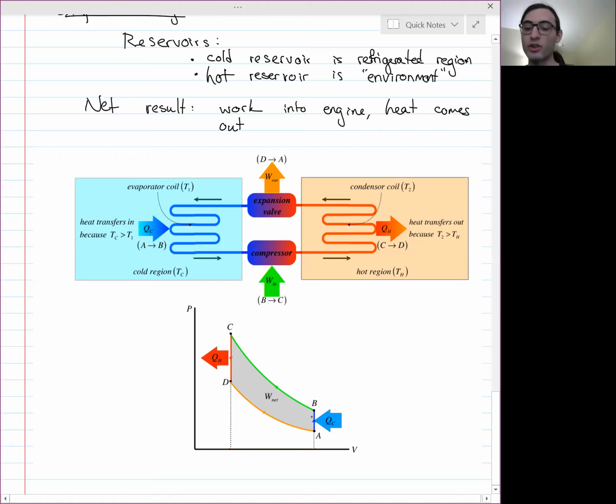Then you start doing work. You take energy input from the outside world, like electricity, and you push on the gas to do work and compress it. That would be an adiabatic process, so no heat goes in or out. Think of a closed syringe that you push on really fast to make it heat up a lot. You do a lot of work to increase the temperature of the gas significantly without letting any of that energy escape.